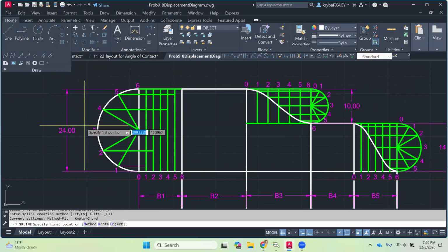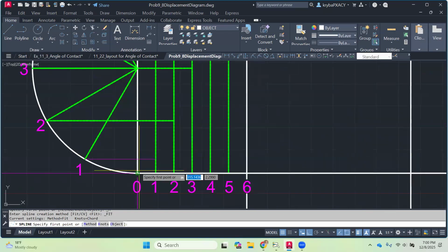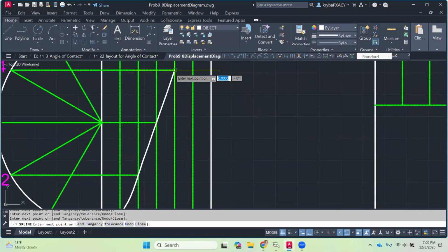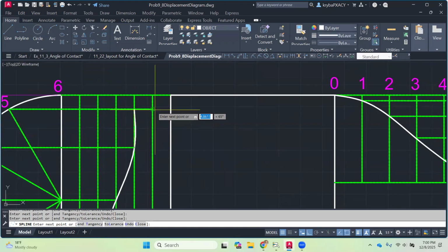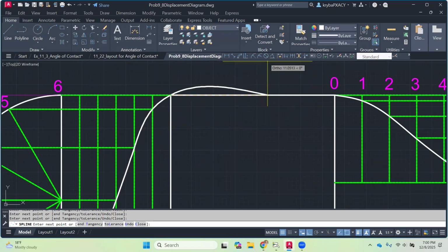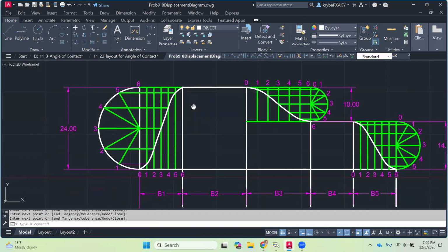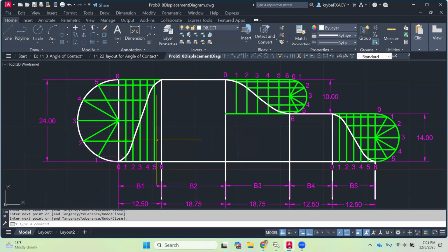Okay, so click on that, and then you're going to grab the intersections at each one, and it's going to gradually create your spline through each one of the points. Once you get to the last one, go beyond and then hit enter. Do not hit escape to end the command. Otherwise you'll lose your spline. Okay. I do it all the time. I did it earlier today and I'm like, that's right. So, and then that's how you get your spline along there.